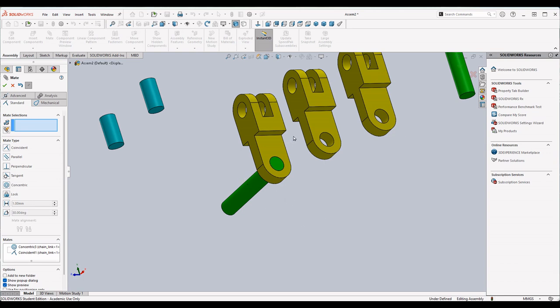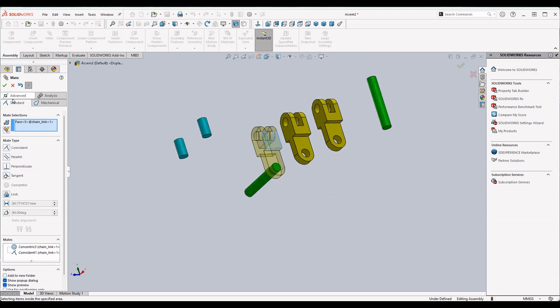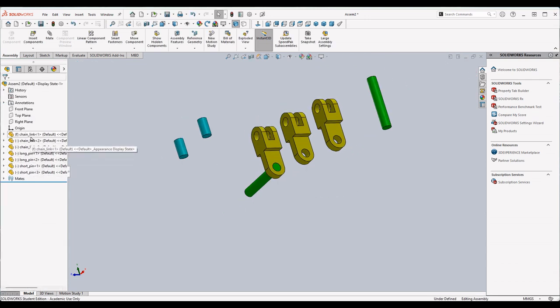All of them have to have 2 to 3 sketch relations, depending on how I'm trying to constrain it. If I do 3 sketch relations, it constrains it in all 3 axes usually, and that means it'll be completely put still. But if I don't constrain it in all 3 axes, then something will be able to rotate. So this is the part that I loaded in first, so you can't move this piece. But this one, you can't really tell, but it is actually rotating on here if I grab it and start moving it. So then what I'll actually do is unlock this piece.